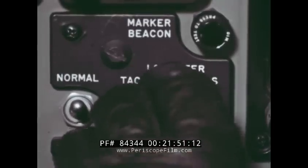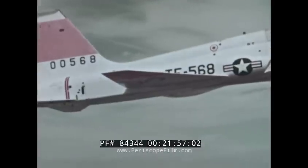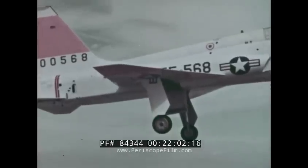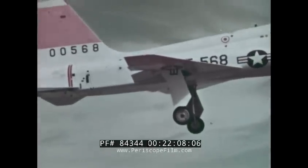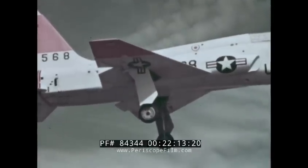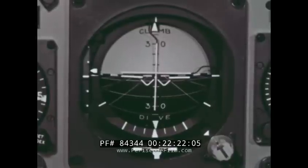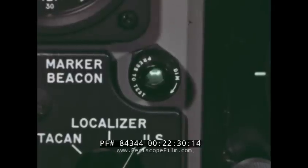Select the ILS mode. The ILS pitch steering bar now appears. Extend the landing gear and 60% flaps. Slow to approach airspeed, which for this fuel load is 155 knots. We're approaching the outer marker. Now we'll enter the glide path.